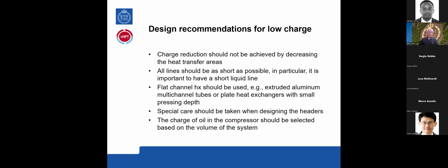And one problem with the heat exchangers is always the headers, because headers could take actually as large charge as the rest of the heat exchangers if you're not careful. And of course, if we use typical standard compressors, there is a large charge of oil which will absorb a lot of refrigerant. And this has to be handled in some way if you want to decrease the charge.